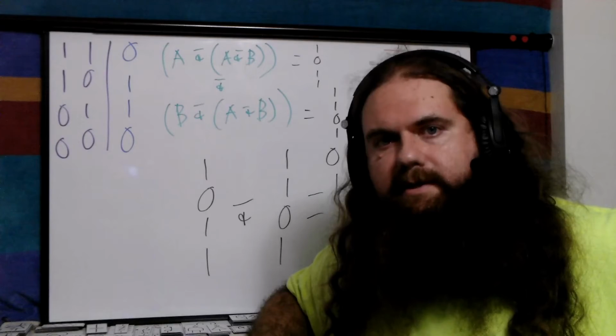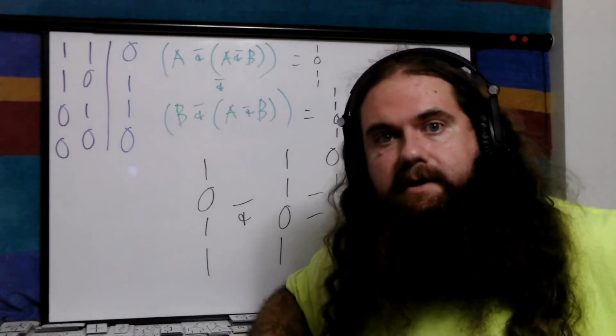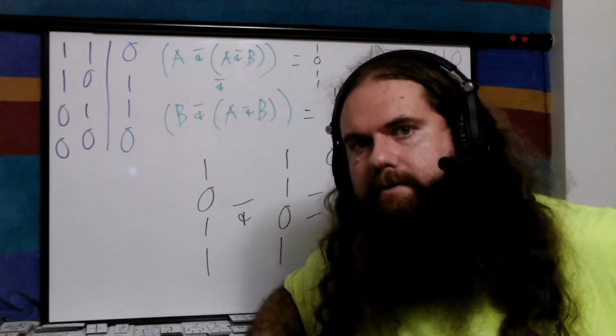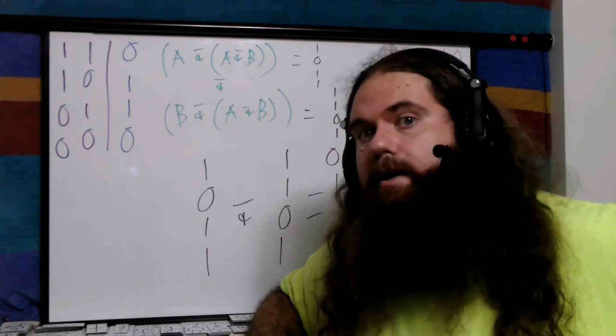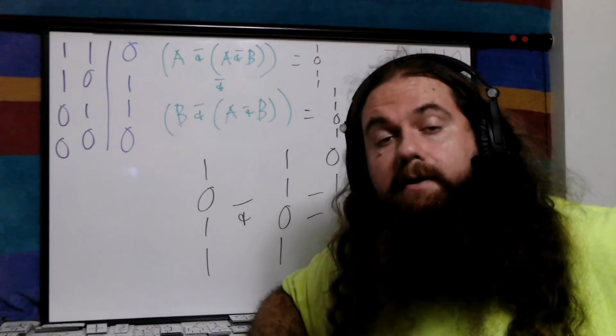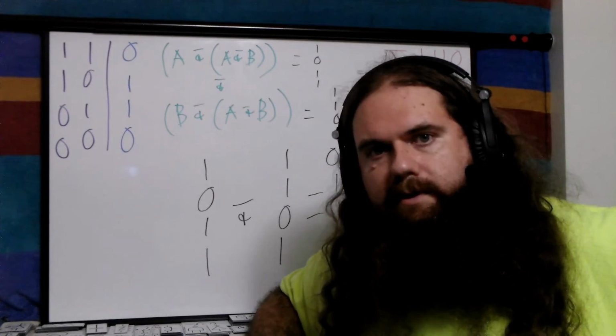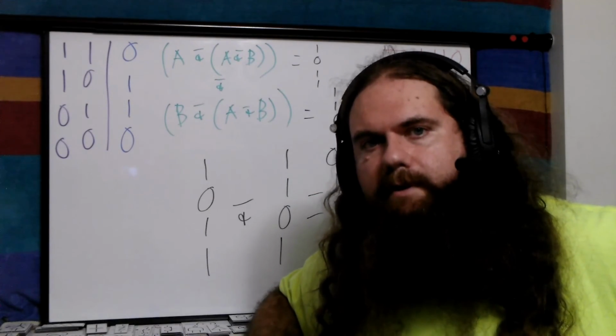If you see a standard chip, you might see 6 NOT gates. That's called a hex inverter. Hex referring to 6 of them, like hexagon. And that's going to be my logical go-to if I ever need to make a more complex circuit. I'll just do it with the NANDs, and I won't have to mess with it.